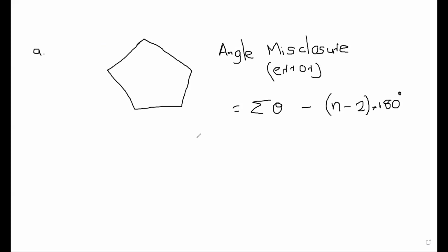Right, so this is the total error, because for one angle you cannot find out which is the correct one. So you have measured 5 angles, and with this total you have ended up with this much error. Then now you have to correct it. To correct, what you have to do, you take the negative of that error. That is called the correction.